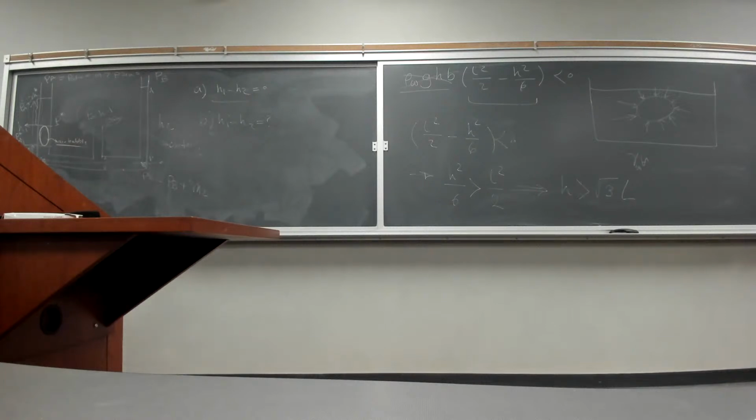So what does it mean? It means that the pressure we have here, if we didn't have the air bubble, P1 would have been equal to PA plus gamma H1. Okay. But inside this column, we have an air bubble that the water is exerting a force on to push it upward, in the opposite direction than the static force.